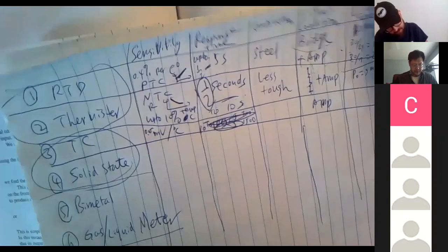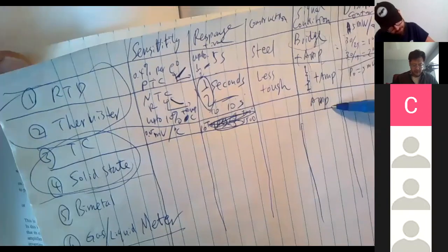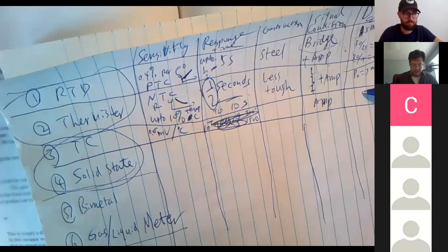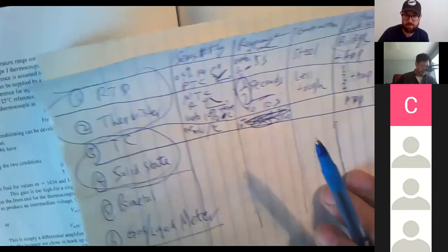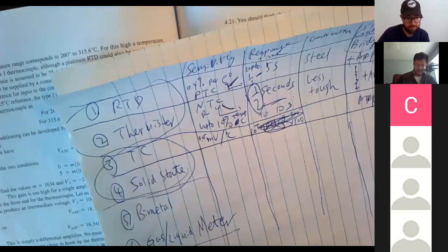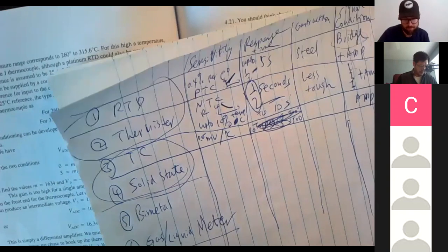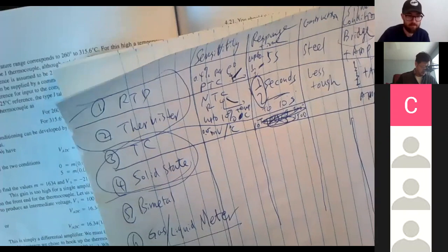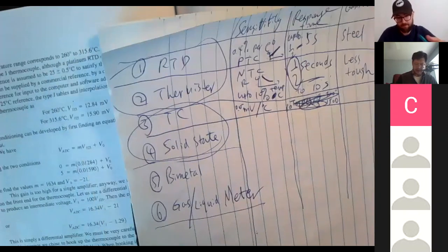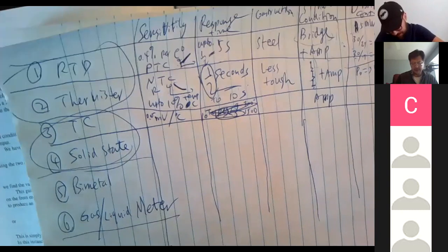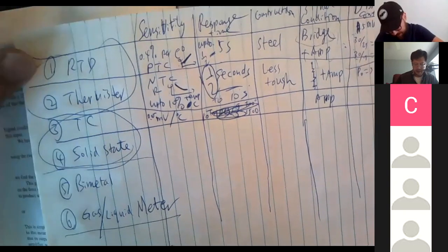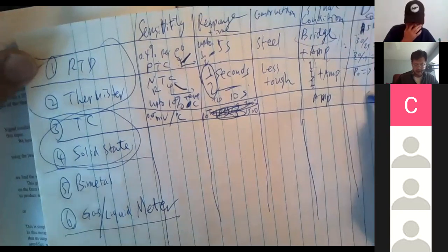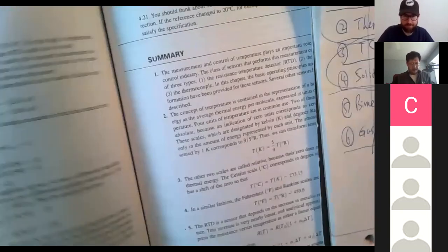Construction, thermocouple, signal conditioning amplifier, dissipation constant. Yeah, we got dissipation constant too, because that sensor can be self-heating also. Maybe that's less of a problem than the previous one, because the previous ones are resistors, so they actually self-heat significantly. So it's probably not an issue here. Dissipation constant. So that's a thermocouple.